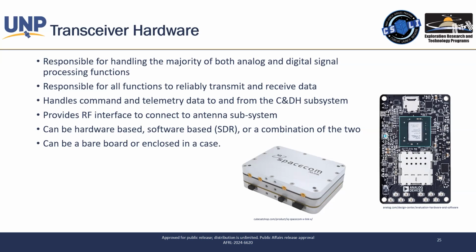The Zynq 7020 is what's called a system on chip. It has an FPGA, but it also has an ARM core. That microprocessor core, you'll define some of the functions, but most of them will be in hardware. Does that answer your question? They're not all that way, by the way. If you ever use an RTL dongle, that's basically purely software. It'll give you a fighting chance with the IQ samples, but your computer has to keep up with the data rate that it's streaming. The answer is it's a mixed bag. Good questions. Any other questions?